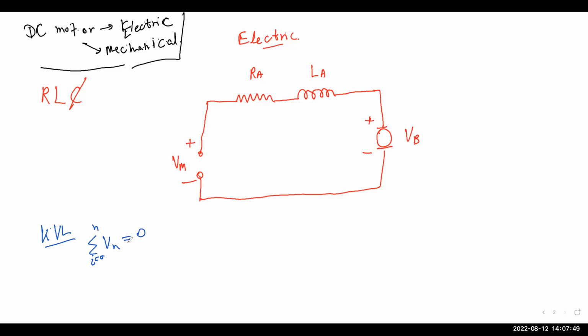I'm not sure how you guys are doing this, but I'll go with the method that I'm following. We'll take the supply here, which is a voltage rise, so we'll keep this as positive, VM. You all have done power electronics, so you know how to check the devices: the side where positive current enters is positive and the other negative. We'll mark the polarities of these devices like this, and assume this is VRA. We'll assume the voltage at this point is VLA, with the current going this way. So there's a drop here, VRA, and then another drop here of VLA.